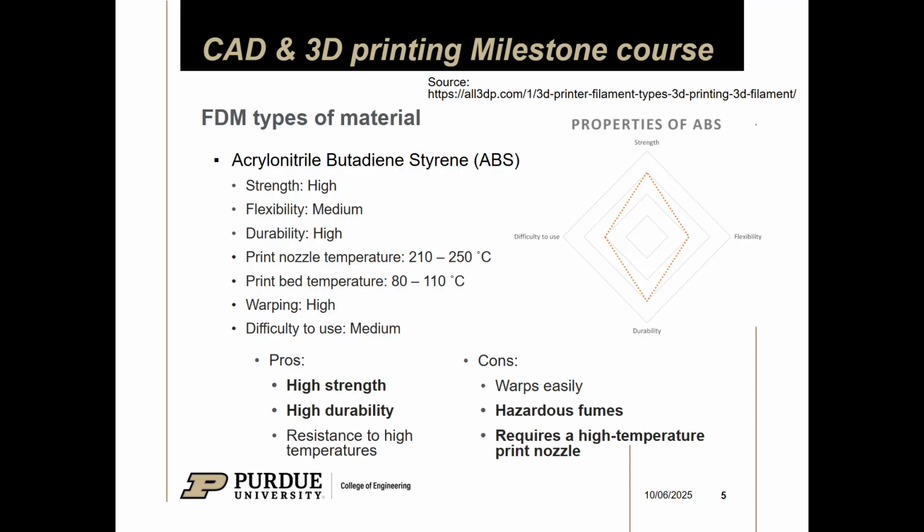But just keep in mind, all material that you print exudes hazardous fumes. Sorry, that's the right word. You can probably smell it, and ABS is particularly smelly. So you might want to keep that in mind. Print in a really well ventilated environment, all the time, but especially for materials like ABS.